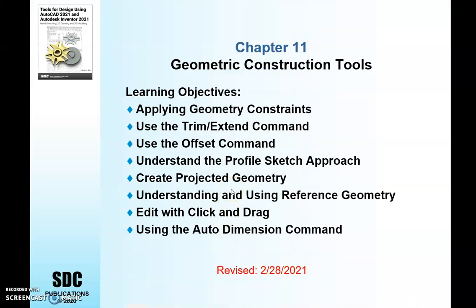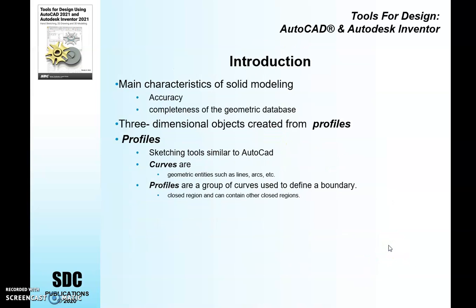This is the lecture video for chapter 11. He's going to have us draw something, and he's going to introduce several things, but particularly the offset command, and then he'll show you a few other things as we go along: how to click and drag, move things around, the extend command, auto dimension command, and projecting geometry. So there's a number of different things.